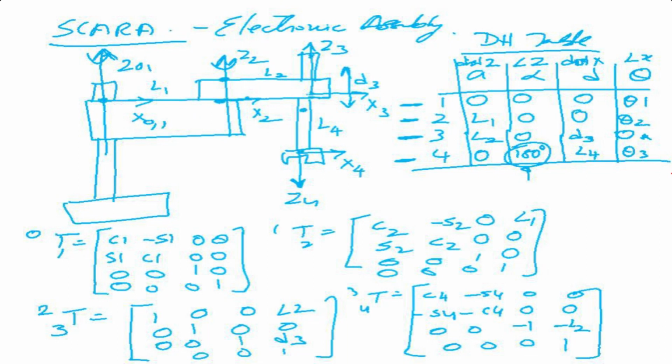Now this is the reason why we need to understand this DH parameter very carefully and very systematically, because the computer program operates like this. So all these simulation softwares, for forward kinematics, inverse kinematics, they operate like this. So this is what we need to understand.